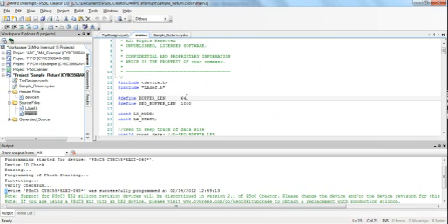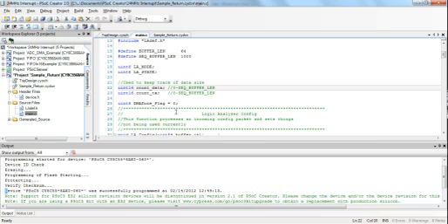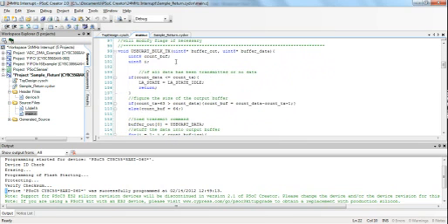I've set the buffer length for each USB package to be 64. I've set the sequential buffer length to be 1,000. Numbers can change. The code is flexible enough. There are a couple trackers to keep track of where I'm counting data and where I am transmitting data, and a DMA done flag. So this is the USB bulk transmit.